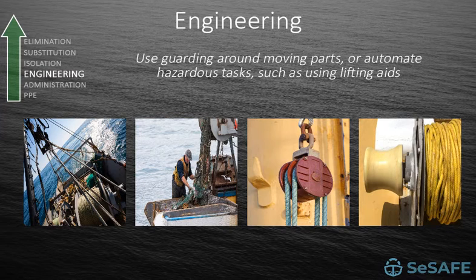Engineering is the next best option and includes the use of holding pens and pound boards to prevent the catch from moving in the hold and affecting boat stability. It also includes the use of hauling equipment to eliminate manual lifting tasks.